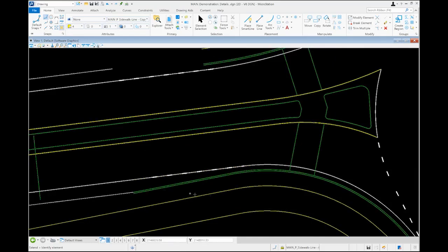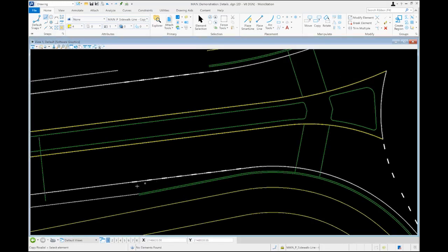Along this section here, as we're tying in our bike ramp, what we want to try to do is get a 30 to 45-degree angle for that ramp established. As we discussed before, we want to try to get that ramp sort of at the top of the taper here, both to allow more time for that cyclist to be able to get off the roadway and make a little smoother movement, but also because that's where it falls within that sort of 100-foot setback from the entrance and 50-foot back from the crosswalk.